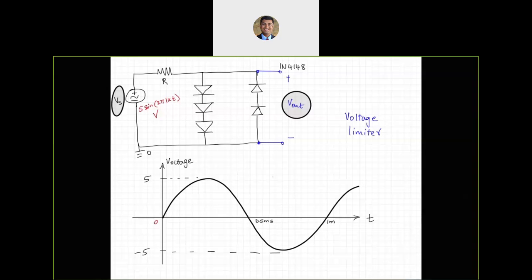Now what is going to happen as you start increasing this voltage on the positive side? So during the time where we are in the positive half cycle, or here and here, well, as you are increasing Vs in the positive direction, these two diodes are in the reverse biased region. However, these three will be in the forward biased region, which means that they will be able to function as three valves that are connected back to back. And I would need 2.1 volts to turn on three back to back diodes that are connected in the same direction.